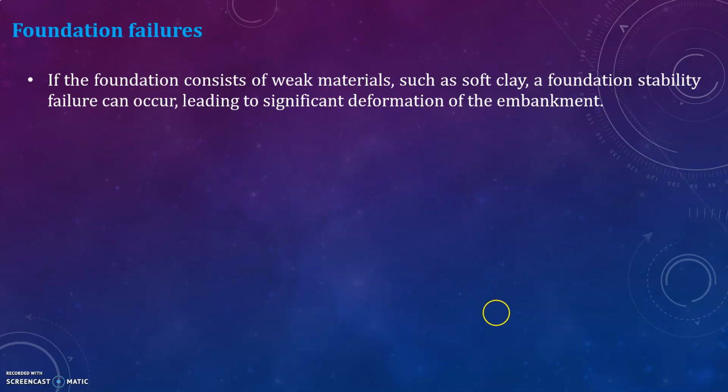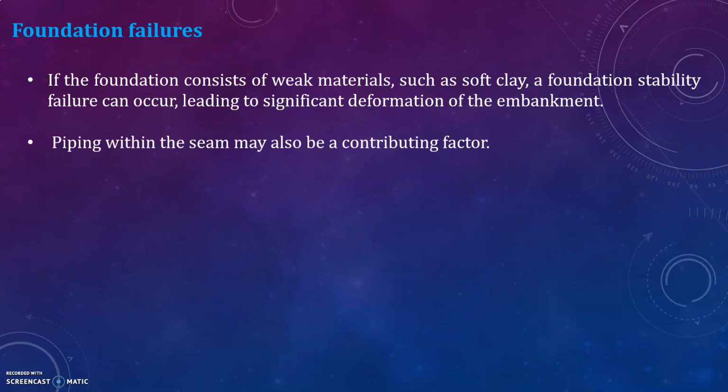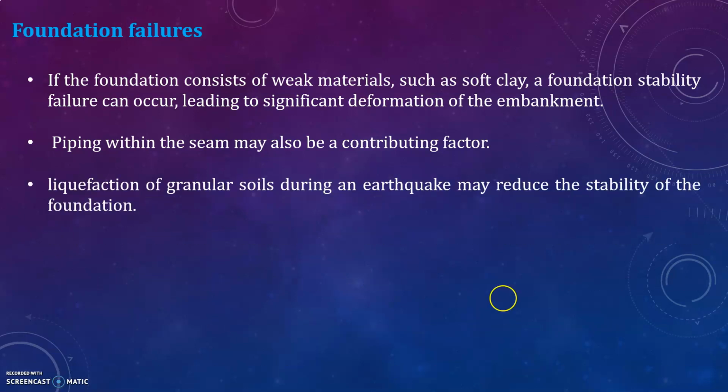Next one is foundation failures. If the foundation consists of weak materials such as soft clay, a foundation stability failure can occur, leading to significant deformation of the embankment. Piping within the seam may also be a contributing factor. Liquefaction of granular soils during an earthquake may reduce the stability of the foundation. Okay, so these are some of the common reasons for foundation failures.